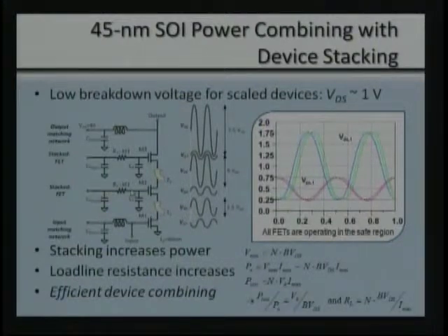And by choosing the value of C2 and C3, we can control how much variation, how much swing occurs at V2. But that variation will be, because of the capacitance CGS, in phase with the drain voltage at the device M1 and the drain voltage at the output of M2. So we can combine all of these drain voltages that are swinging across each transistor here in phase to get a very, very large voltage swing at the top of the last device.